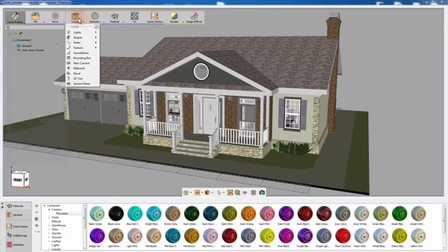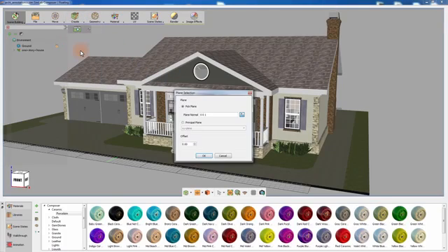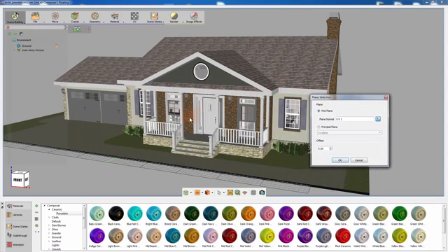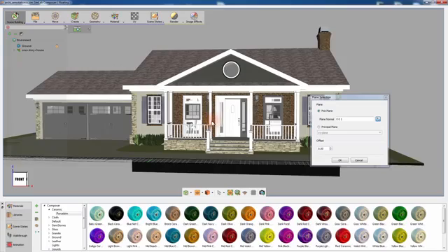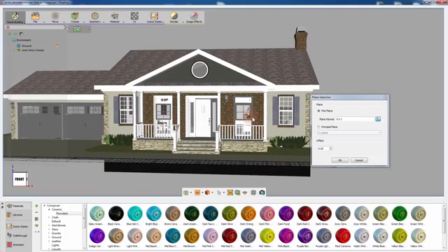Go to the Create menu and select Annotations. The Plane Selection dialog will appear. In this dialog, we are going to determine the plane on which we are going to create the annotations. Selecting the proper plane for the annotations creation is crucial in terms of where the annotations will be projected for viewing. Since we are going to add measurements for the front elevation, we need to select X or Z plane, or simply click on a parallel face to the front view.